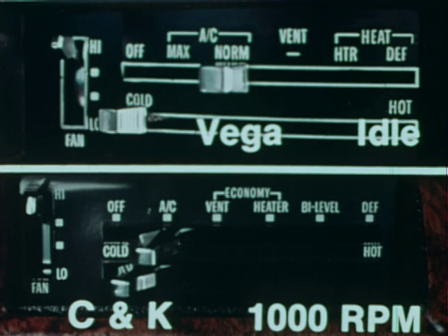One of the first things a technician needs to know when diagnosing an AC complaint is whether the refrigeration portion of the system is operating properly. Since the OTCC system does not incorporate a sight glass, the following refrigerant quick check method can be used to determine if the system needs additional refrigerant. To use the refrigerant quick check procedure, first start the engine and wait for the thermostat to open.